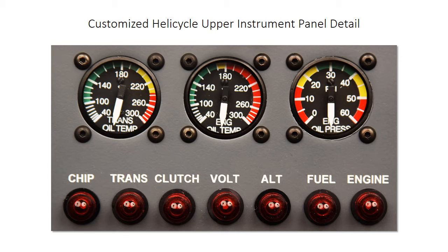Each one's an 80 mil lamp. Comes out to about 1 watt. They're fairly bright. They have a wider field of view than LEDs, and that's why I went with incandescent. LEDs, when you look directly at them, a lot of these indicators look very bright. The problem is that these are not at eye height. They're well below, they're down by your belly button or your chest.